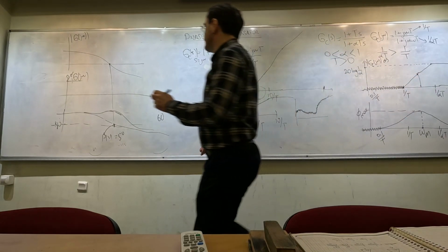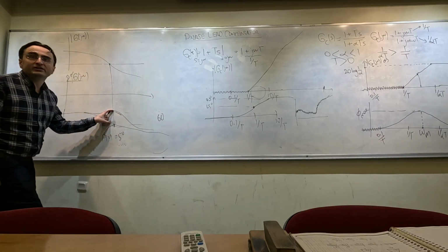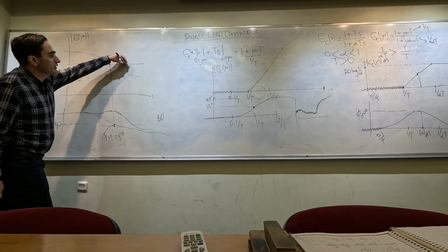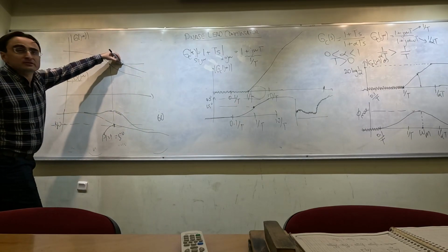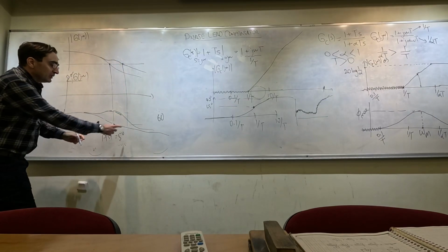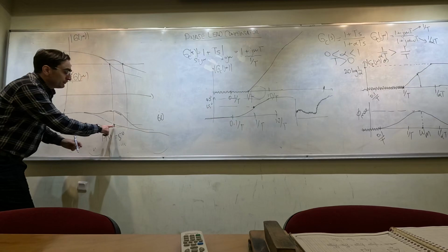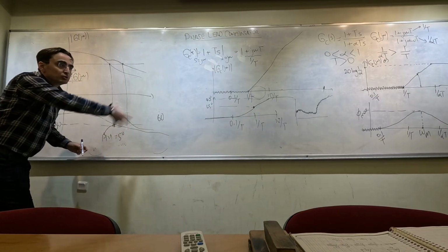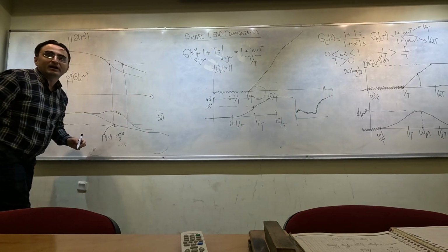This means that as I try to increase the phase margin of the system, the gain is going to increase as well, and the gain crossover frequency of the system is going to shift to the right. And the phase of the system is going to be reduced slightly there, so I'm going to lose some of the phase that I added.